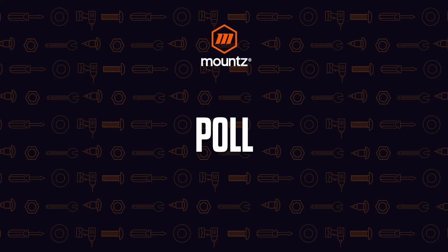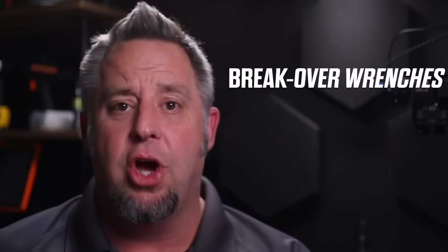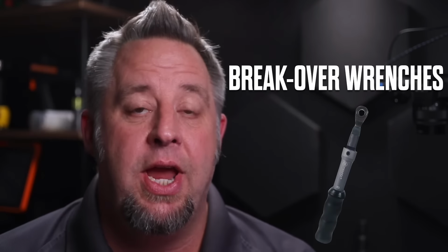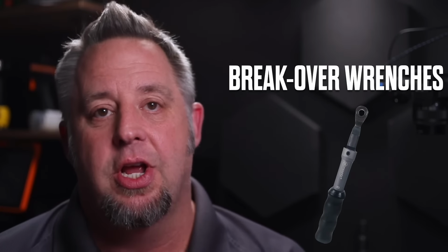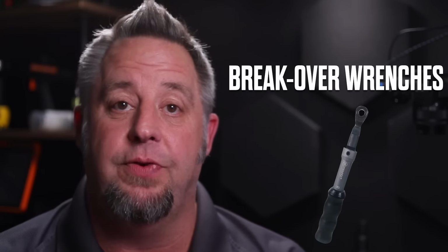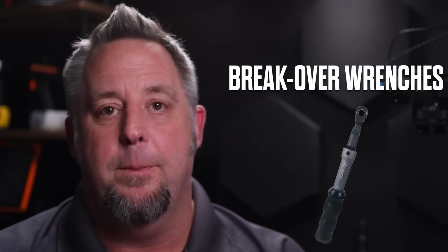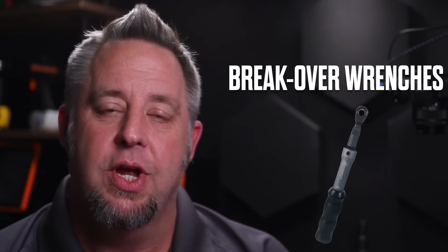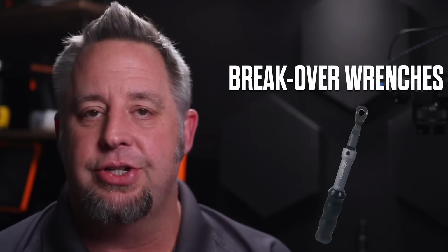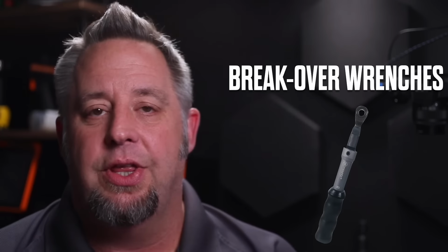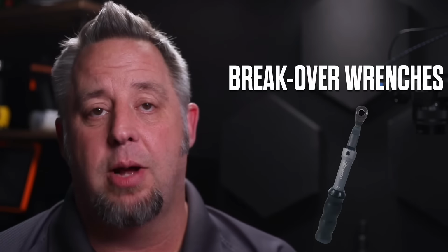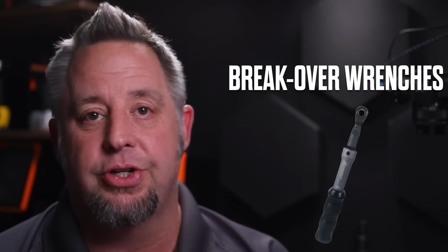All right. Thanks very much for participating in the poll. It looks like everyone that is using the click wrench, it seems to be doing the job for them in their application. So it's always good to know how operator dependent it is when you're using the click wrench. And so if you are seeing any type of issues, that may be where you'd want to look. And so some of the other styles of wrenches that we work with and deal with that can help alleviate some of those problems. The first one is going to be a breakover style wrench.